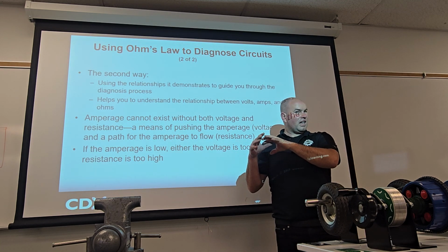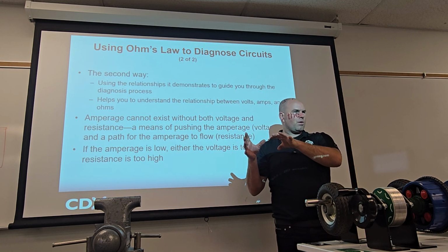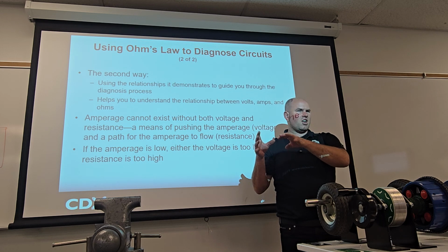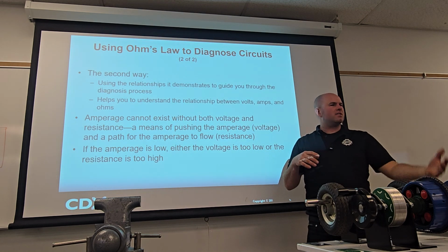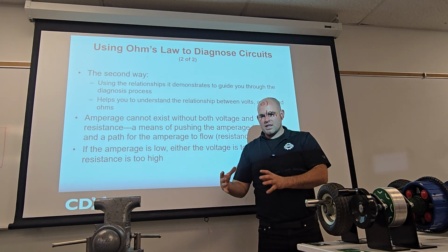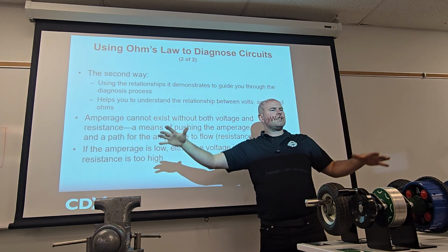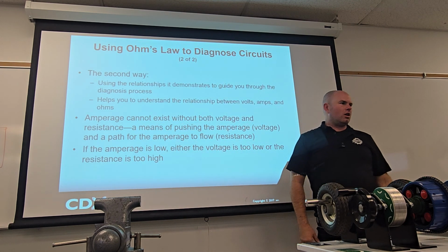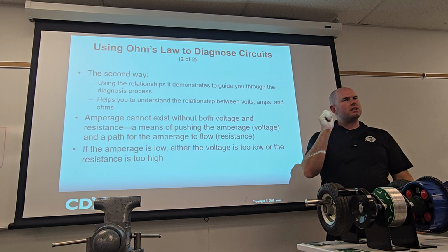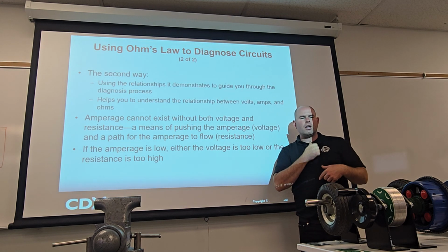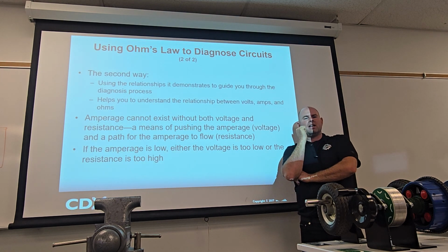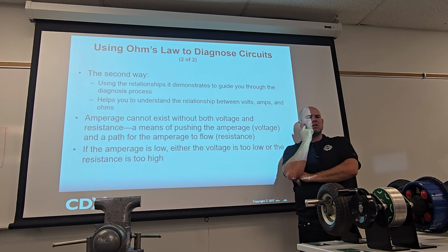battery. And if the battery voltage is low, would it be one bulb that's dim? No, because now you understand the series parallel type of thing, right? So if it's the battery that's dead, everything is dim. The windows are slow. The car won't probably start. Makes sense, right? So when I roll up to the car, I can pretty quickly say, oh, that headlight's dim. There's excessive resistance in the circuit.